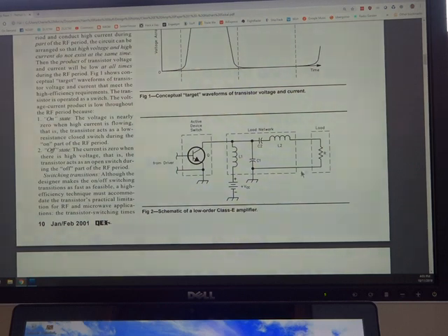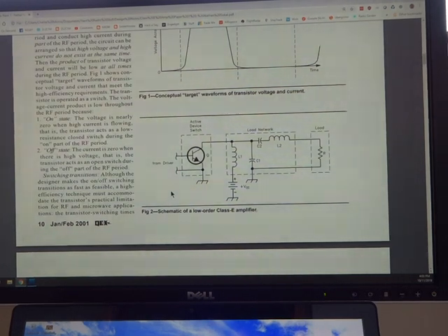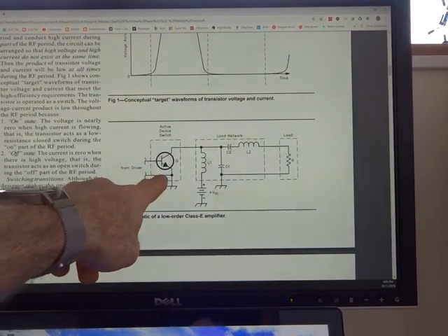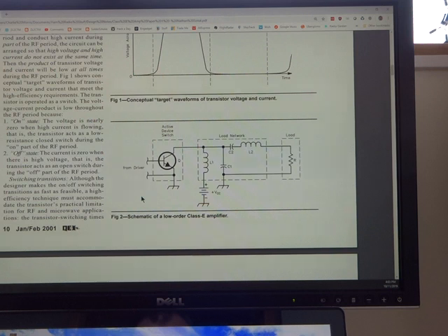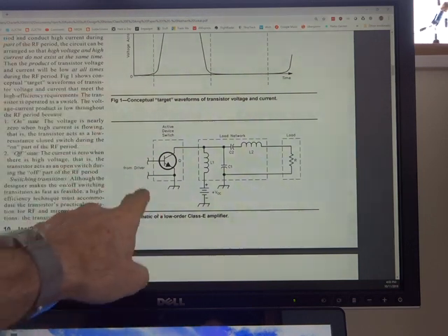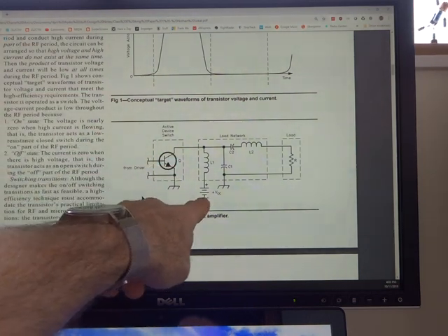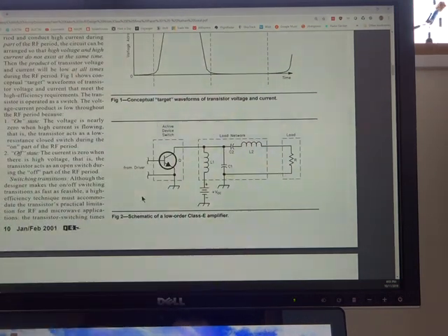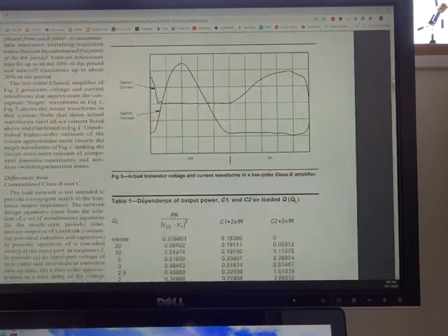I'm pretty well going to play around and have another go at that with a slightly higher power. My thinking is that for the device I'm going to use, just for starters, an IRF510, potentially an IRF540, but we'll start with a 510. Wanting to have a VCC of 12 volts if I can, just a nice simple voltage, and looking to have a power out of around 10 watts if that's possible. So that's the plan.